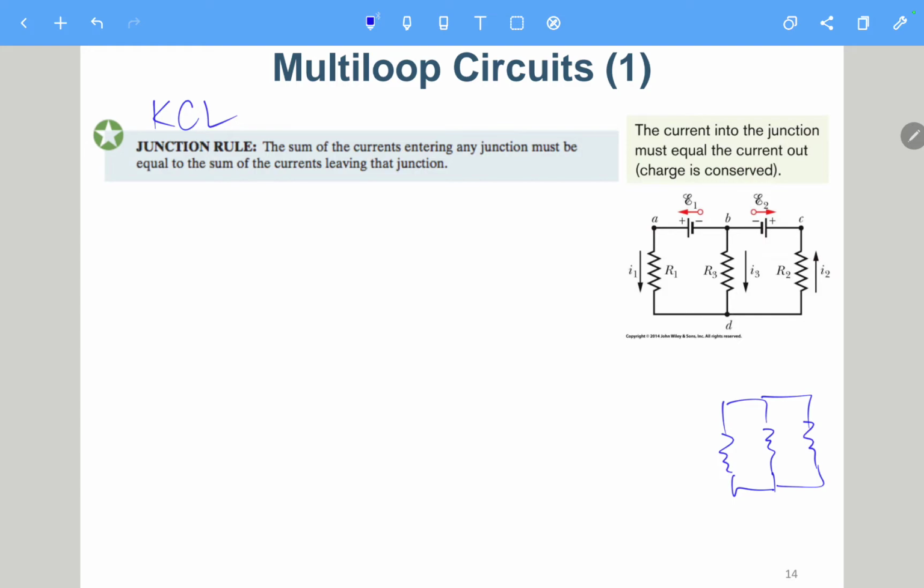In this case it is parallel, but this one is not, because we have the battery in between, so they are not in parallel. If I just move, for example, if I have only one battery, then we can say these two resistors are in parallel, but not for this one. Okay, so you can just change this to a parallel resistance, and then finally you can find this one and this one are in series. So you need to be careful to distinguish whether the resistors are in series or in parallel, or neither of them. Okay, so in this case, we try to solve this circuit.